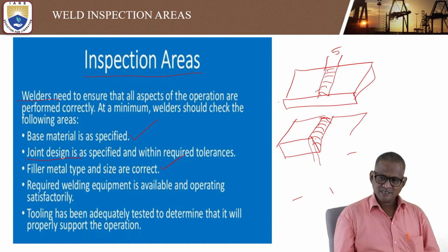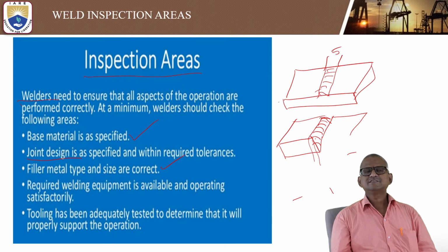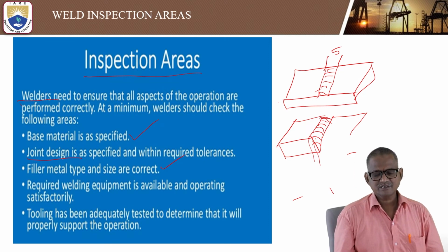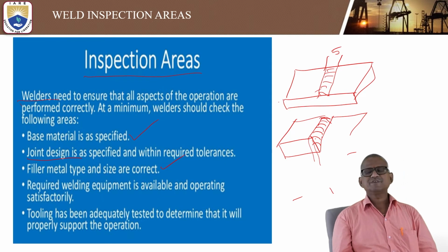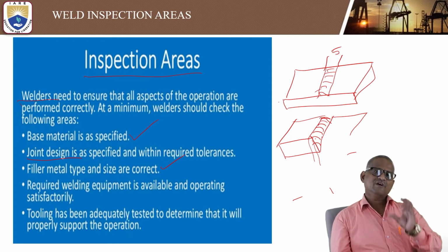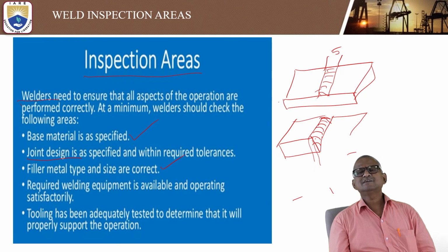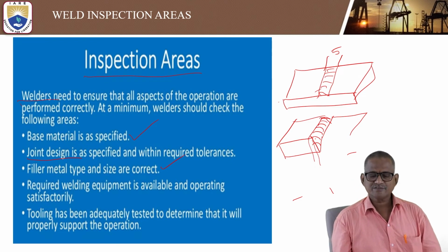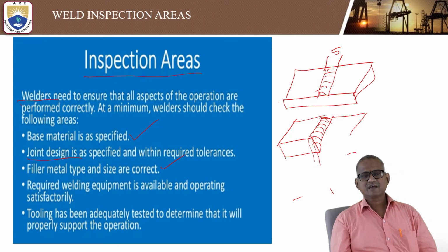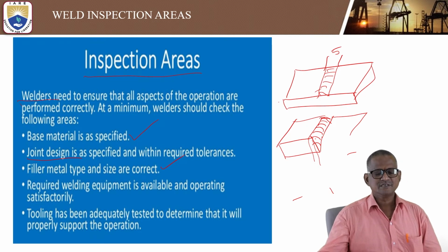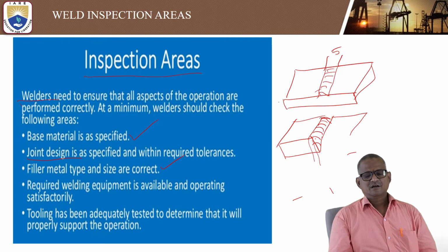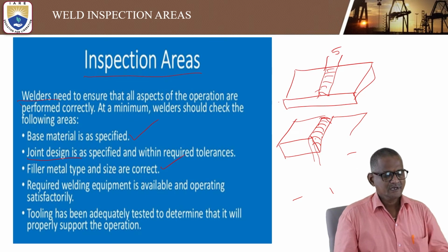If it is an AC welding process, there is a neutral, positive and negative, and again you can test whether the earth component is fixed or not. Okay, if the equipment itself has any problem, obviously the final joining fabrication of the component may also have some defect. So that is the requirement of welding equipment, and you should maintain it properly.